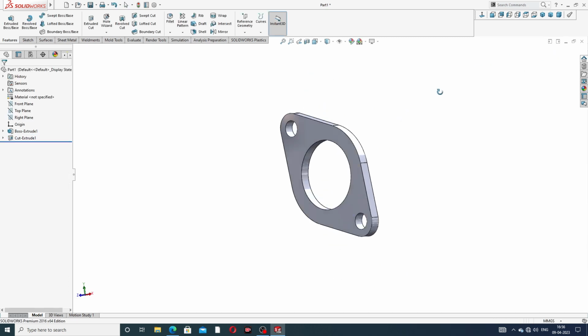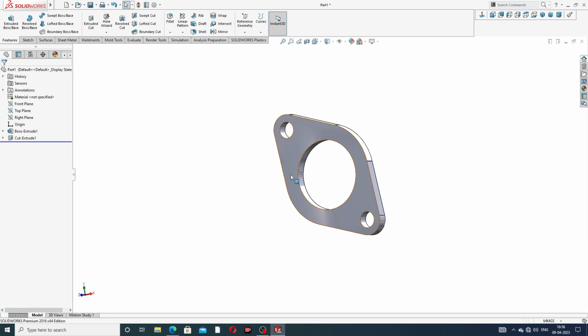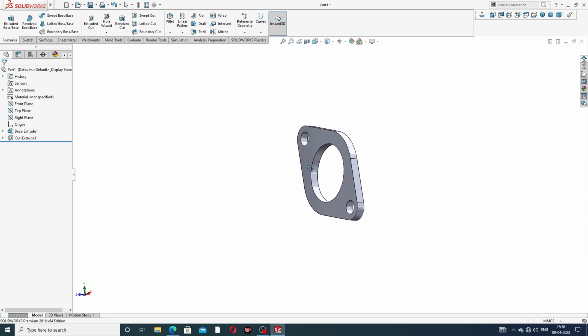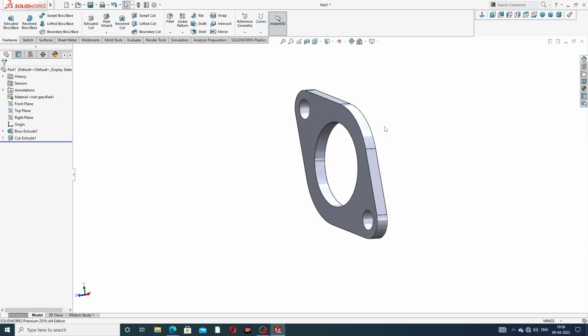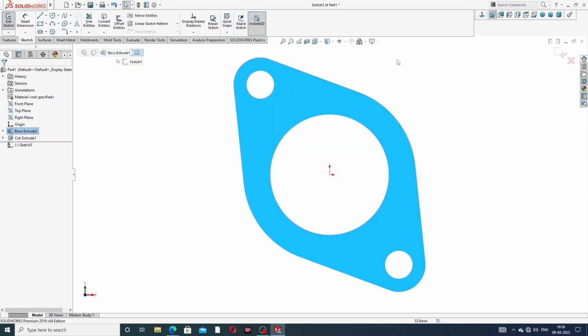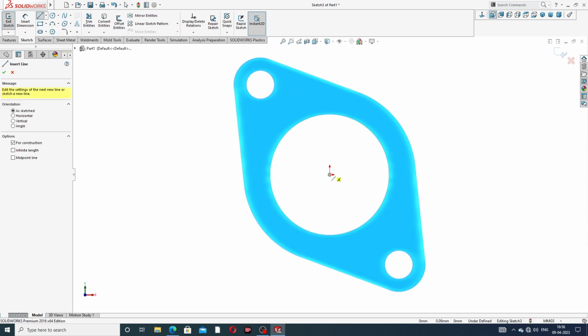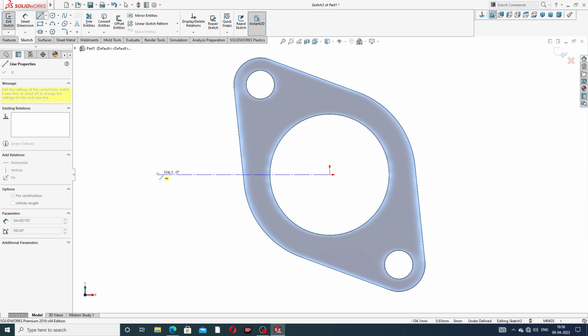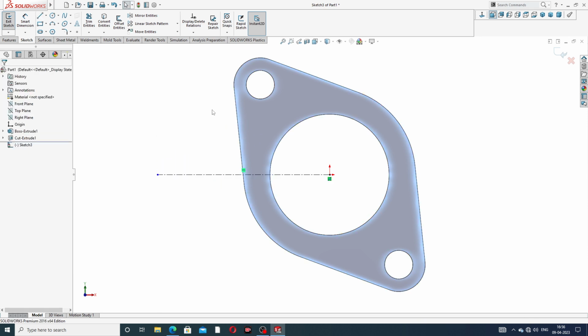This is perfect, and all is a clear one-body design, but use a pattern, and the pattern is 4, and the bodies are 4. And select this face, sketch normal, and use a reference line. The reference line is very important, because this is used for the pattern, and this line is horizontal. This is perfect.